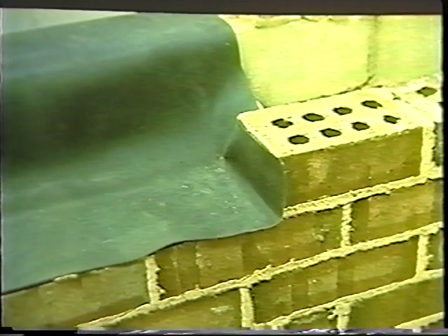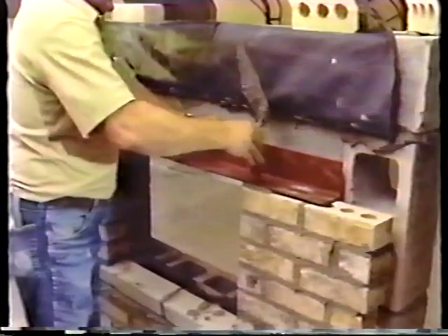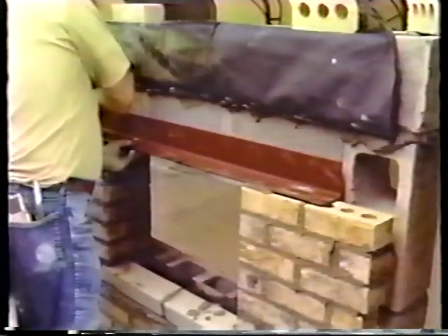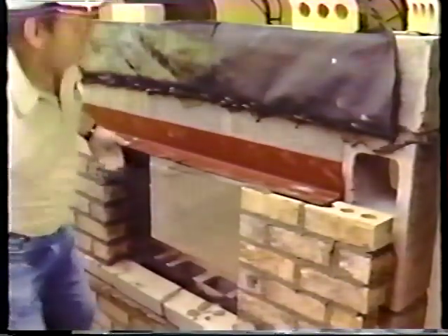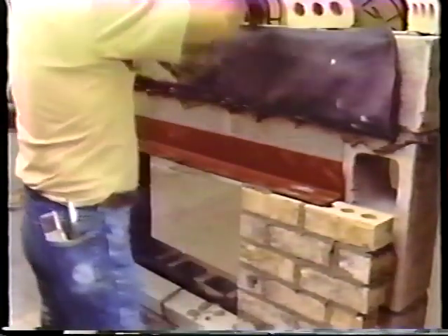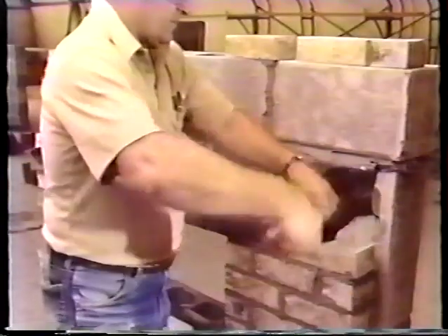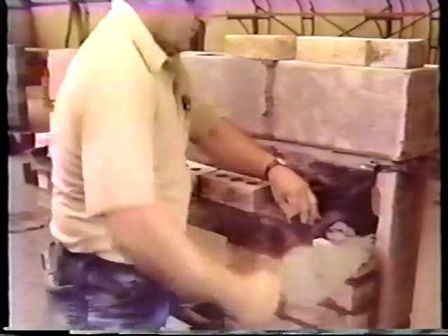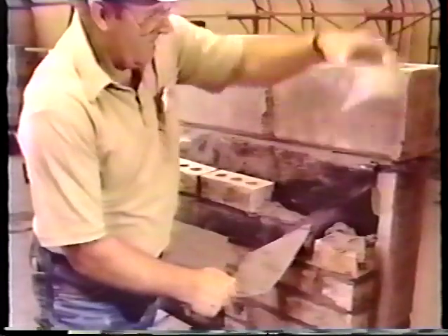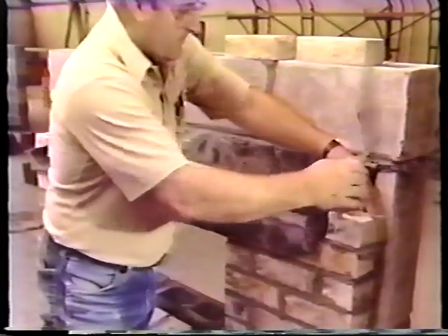Since water can flow along imperceptible slopes, end dams and sealed flashing are critical. Where flashing is not continuous, such as above windows or at window sills, the ends of the flashing should be turned up to form a dam. The end dam forces water back out of the wall through weep holes. The end dam only needs to be turned up a couple of inches into the head joint.